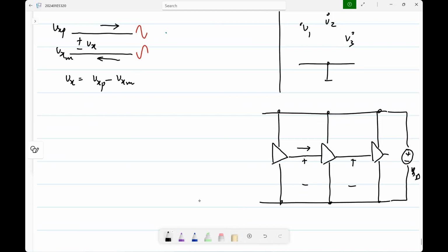So now I can be a little more explicit and say that the output voltage is available between its output node and this negative rail. What the following stage senses is between these two, or it could be between those two also. For instance, if you have an NMOS common source amplifier, the source would be tied to the lower rail. What is the NMOS common source amplifier sensitive to? Voltage between the gate and the source, that is between its input terminal and the lower rail, assuming the source is tied to the lower rail.